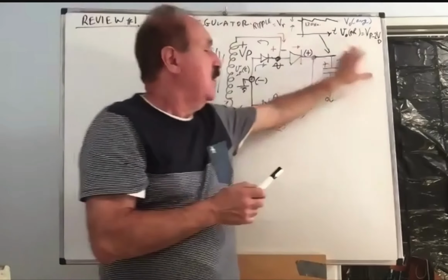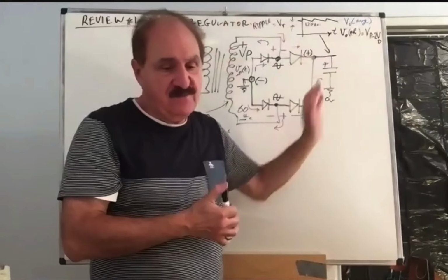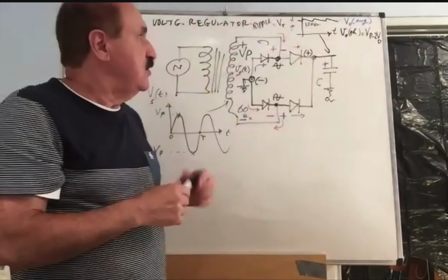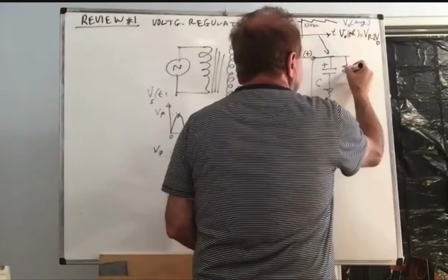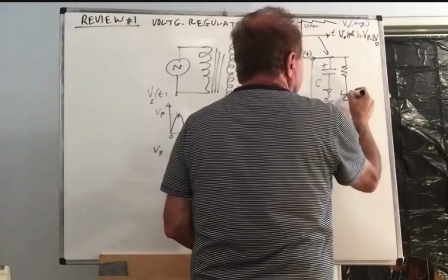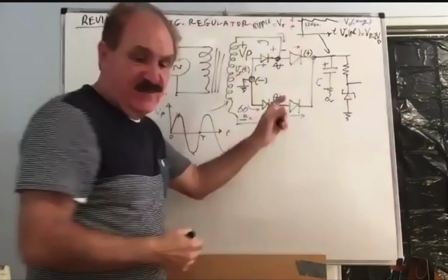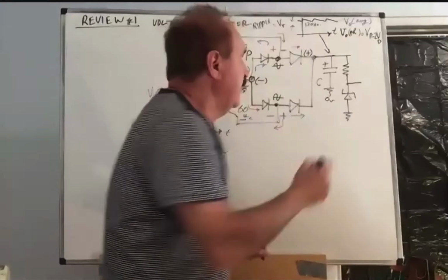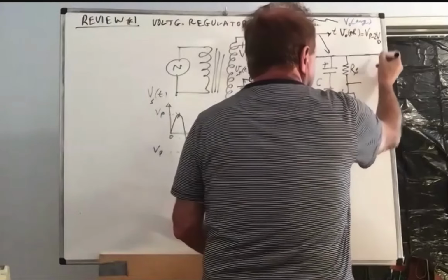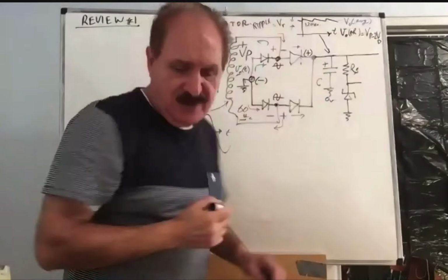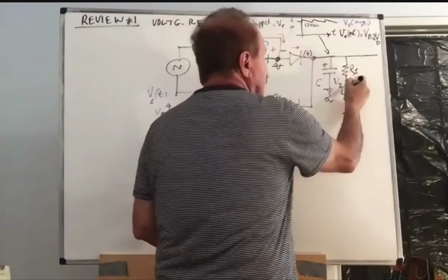Now, this is said about the AC into a DC conversion. Pre-regulator. Pre-regulator is nothing but a resistor with a Zener diode. So what's the function of that one? We call this RS, the series resistance. And that one is the VZ, V sub Z, that's the Zener voltage.